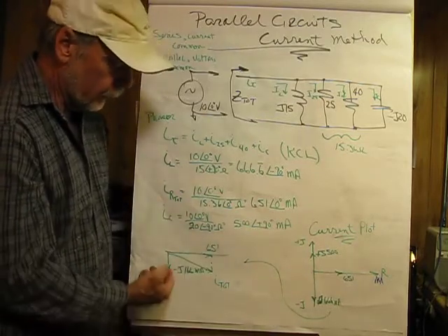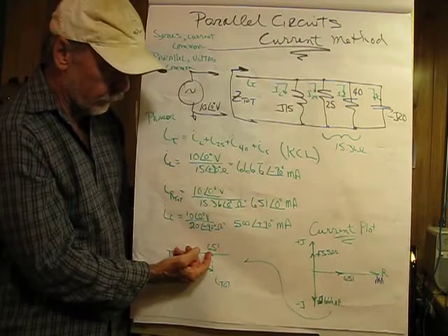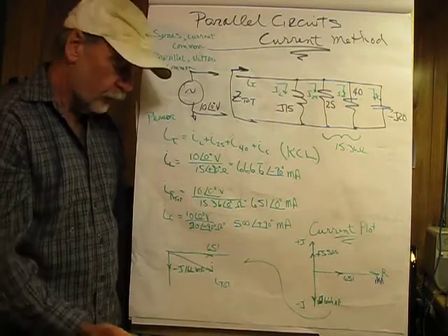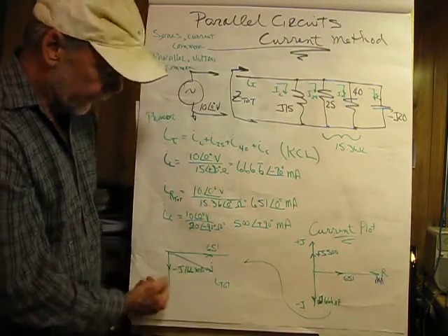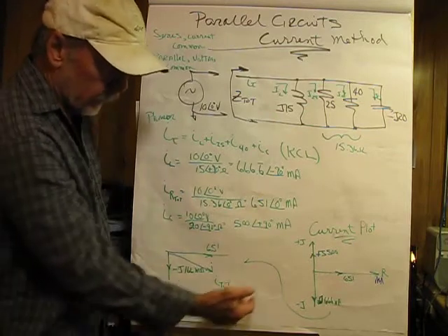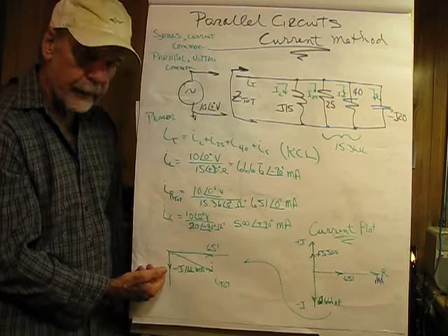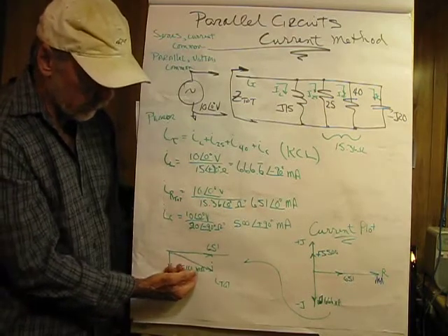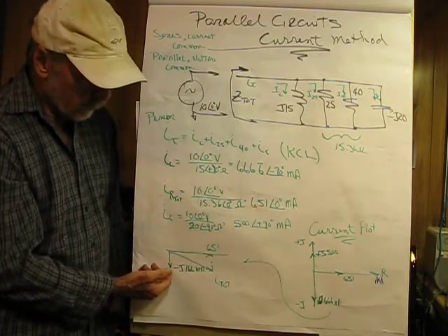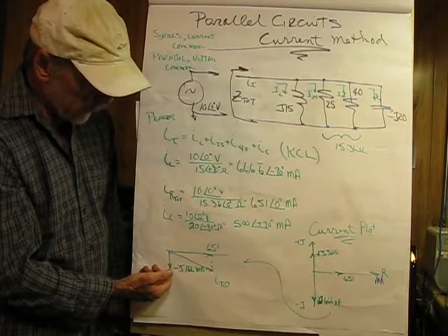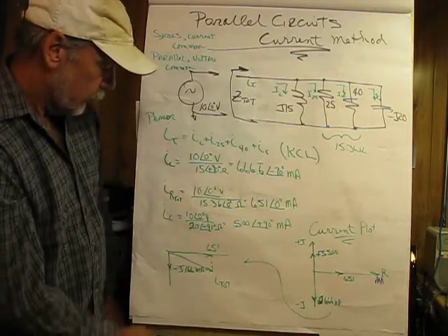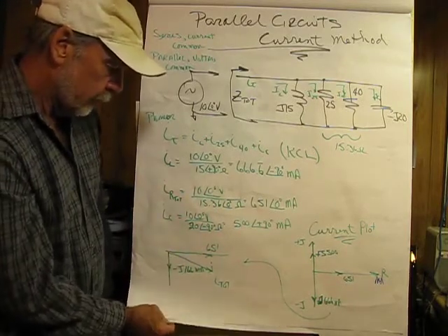And the net result is we have a resistance value that's the same, 651, and the sum of the capacitor current and the inductor current leaves us at negative j166 milliamperes. So what we would need to do then would be find I total, and we'll be doing that in a minute.